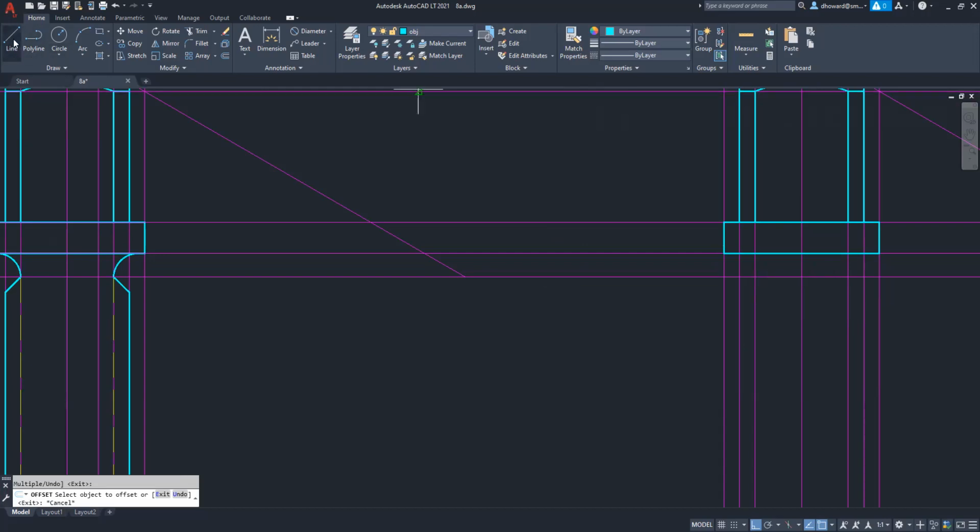And we could just draw that with an object line right now if we wanted. It'd be like this from here to here. So I got those two lines, and then I can go to fillet, F, enter, R, enter, 3/32, and then fillet those two little pieces like that. So that is how you would create that. Or you could just have drawn a 3/32 arc, of course, or circle, and then trimmed it out. Lots of ways to do it.